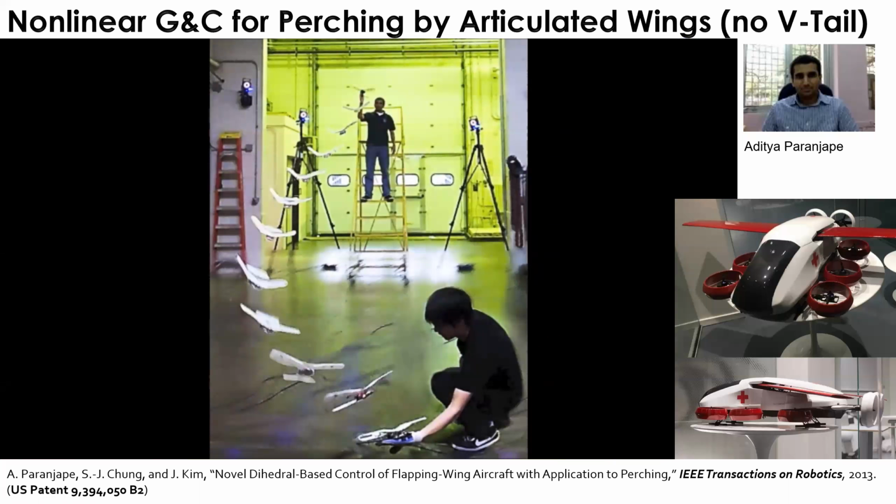And then they can be formulated as a parameterized time delay between elevator deflection and aileron deflection so that you can control the shape of your 3D turn maneuver, and they can approximate this optimal control solution to complete the 3D turn. Again, you can combine the aggressive turnaround maneuver with forward flight, and that duly takes into account this actuator time delay, and then we can plan a very fast maneuver in an obstacle-rich environment.